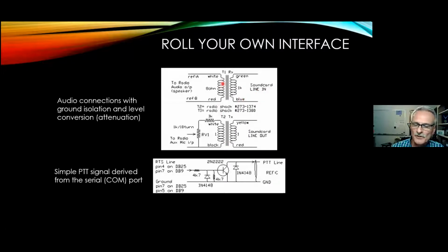The transformers in use here, and by the way, this circuit came off the internet from way back when there was a Radio Shack and you could go down and buy parts there. These transformers are put in here to isolate the ground between the radio and the computer. And I'm going to talk about that in a little bit. But this is providing me with my transmit audio and my receive audio.